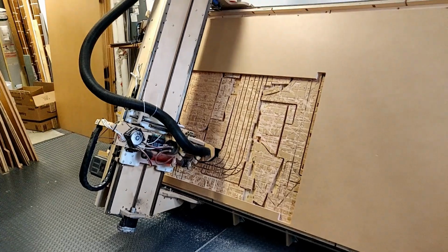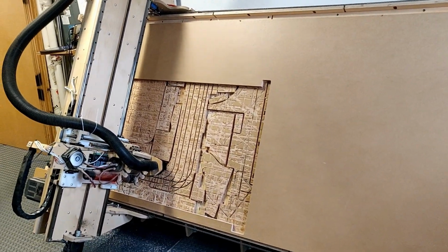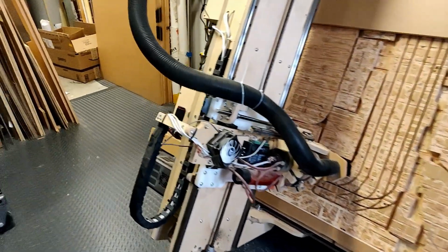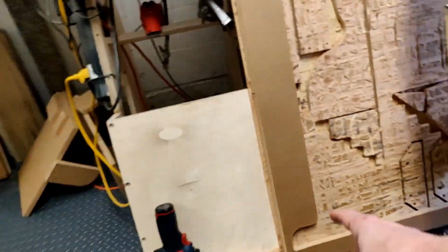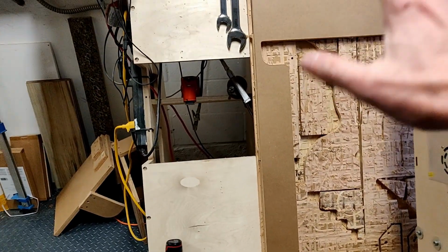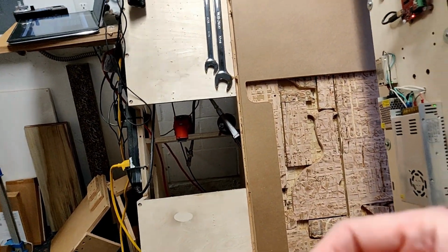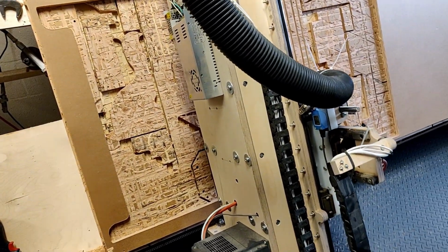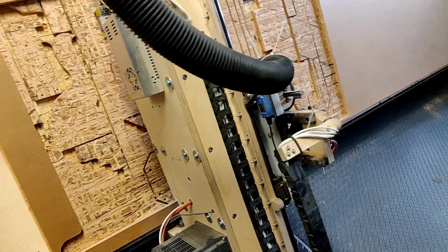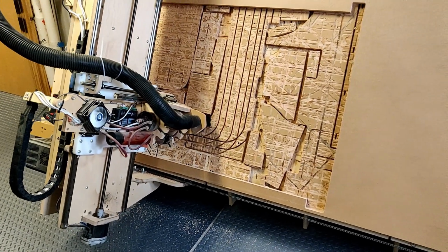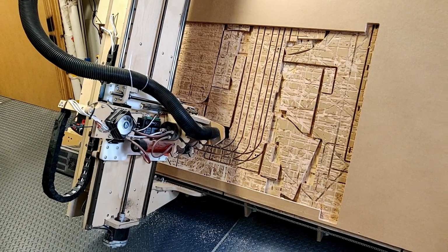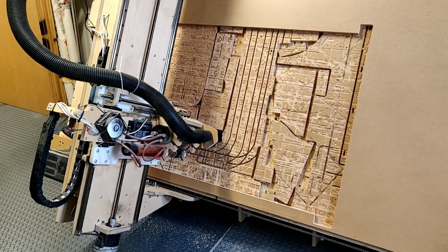So generally on a CNC router, there's going to be a specific point of origin, and I generally have this as the origin, my bottom left, or on a flat table, it would be the one closest to me and probably to the left. And I do this because it's the way I look at things on the screen of my computer, and it makes it safe for me. The machine is going to move in the way I would expect it to move.